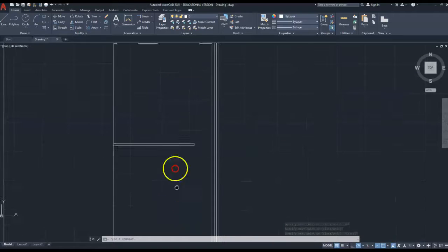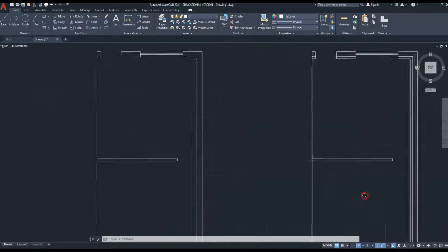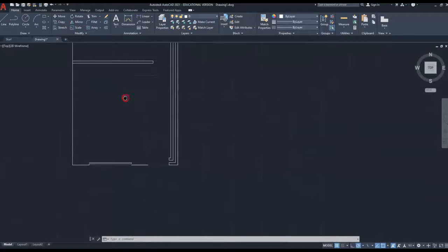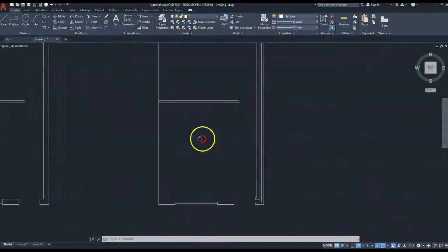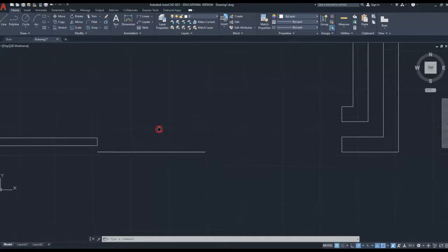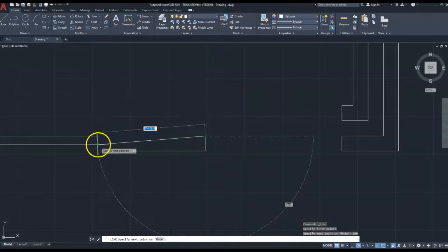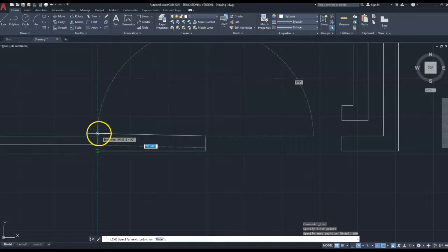I'm going to do exactly the same on the front elevation. So I'm pressing the wheel down and holding it down, and that means I can drag everything around as much as I want. I'll do that a little bit more so you get a little bit seasick. There you go. You're welcome. And so now I'm going to click on start, the line again. I'm going to repeat the process. So we're going to go 100mm. Bring that snap line in to there, return that.